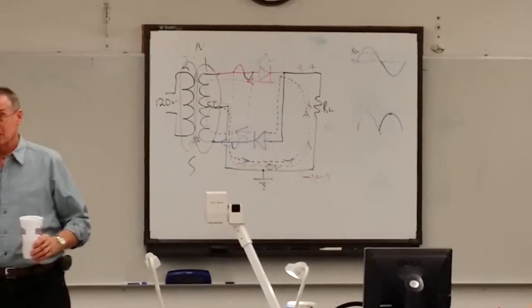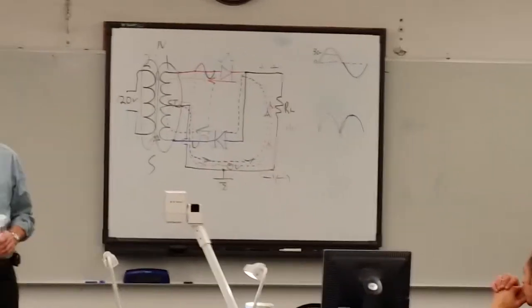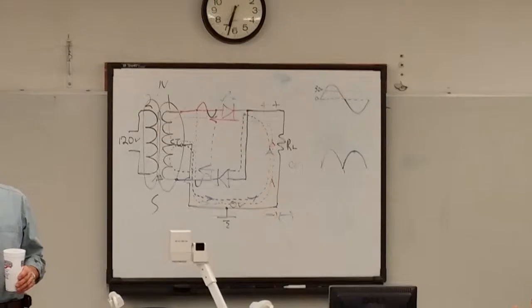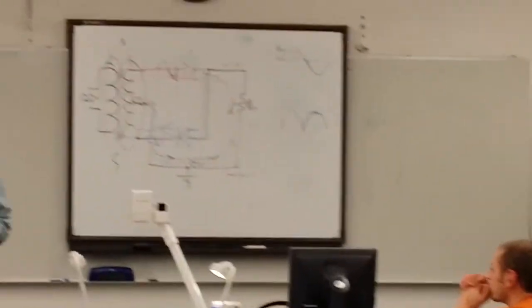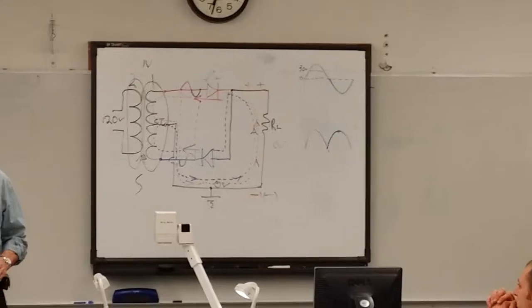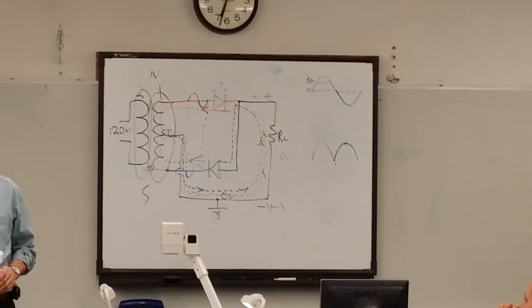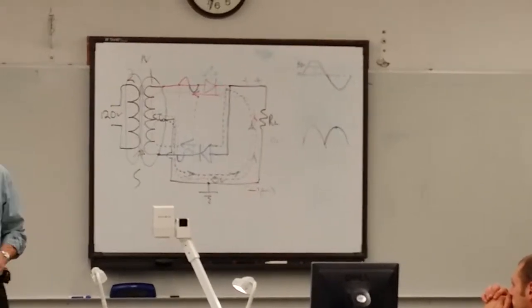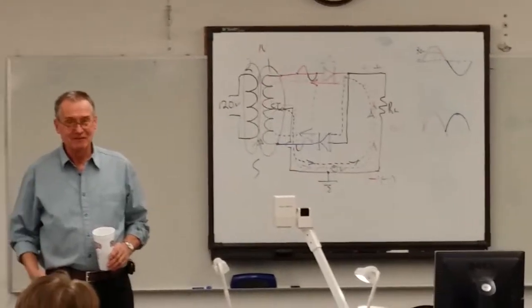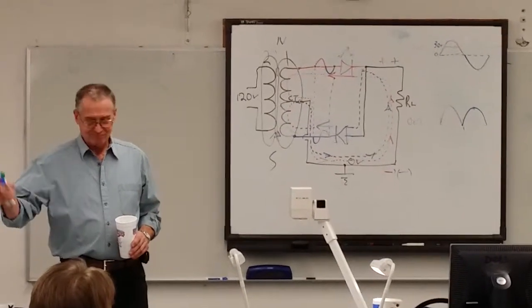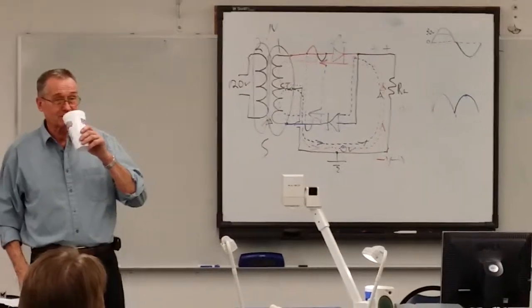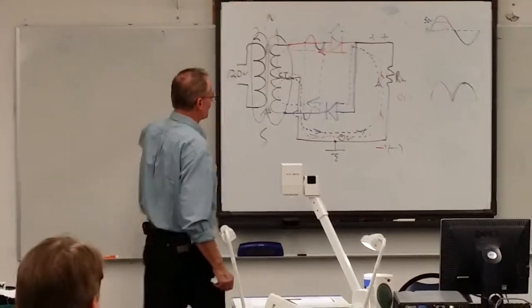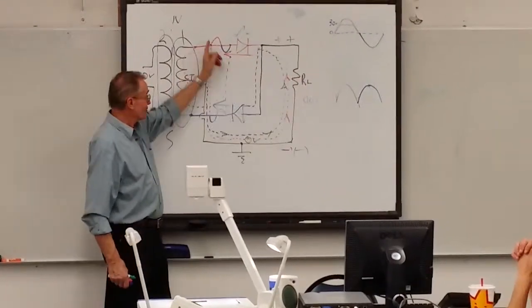The transformers on our trainers, I've heard them sitting there vibrating. I say, "Whatever you do, shut it off quick. You're burning the transformer." It's starting to shake, I can feel the vibration, you can hear it. I'm saying, "You got a short, guys. Shut it off quick." And the diodes both smoke because there's nothing to limit current other than that pretty low resistance secondary winding. That's the only thing that's limiting current. You have to force it through the load. If it doesn't go through that load, it's a direct short, right?